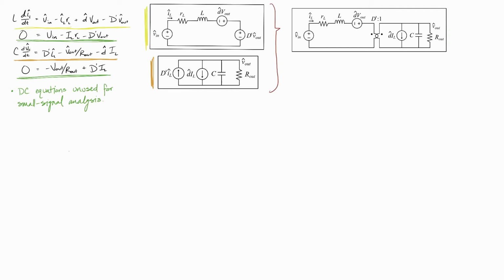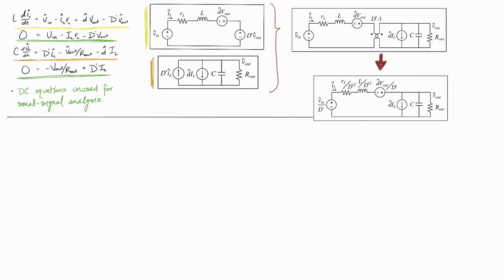So this idea of a small signal transformer is it's not a literal transformer, but it carries the same principles as a transformer in the sense that voltage and current here in the small signal sense are changed as parameters travel across it. We can then reflect impedances through that transformer and get this final equivalent circuit that we see here that I'm outlining in red.